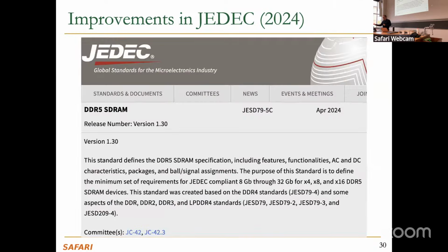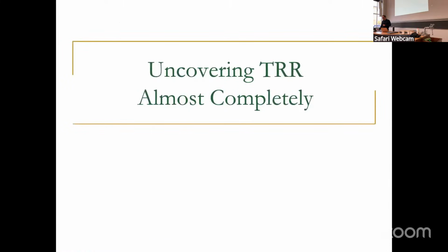And more recently, industry introduced the per row activation counting, where in each row of a DRAM chip, an additional set of DRAM cells are added, and these DRAM cells track the number of activations that happen to that row. And for each row, you have this overhead, basically. Okay, we're going to talk more about that. We're going to see whether this proposal, as it's proposed, is actually good enough. And we're going to see that it's not necessarily that good.